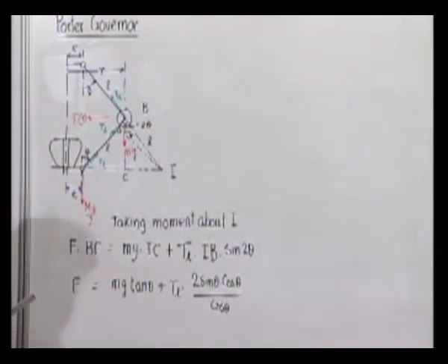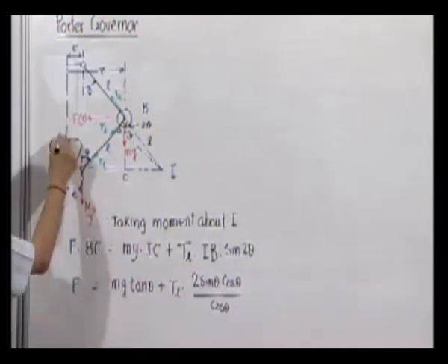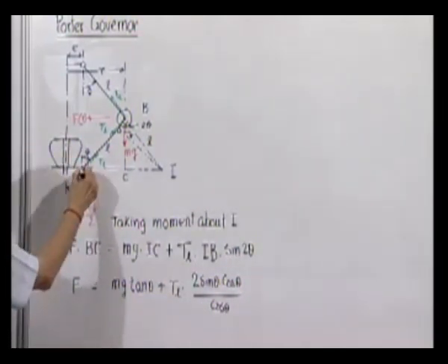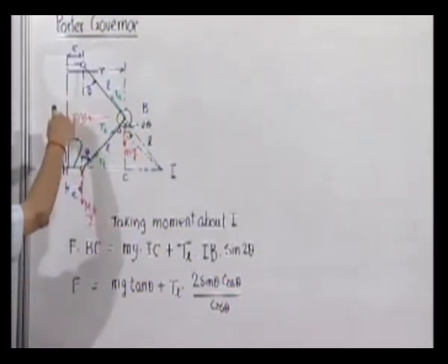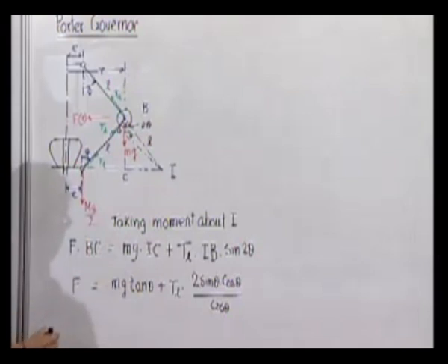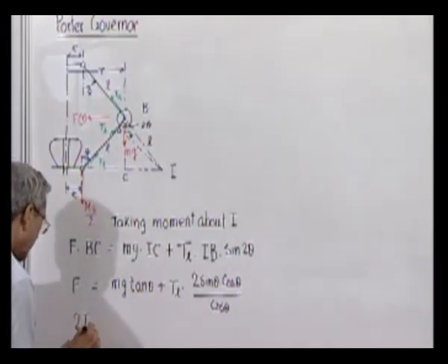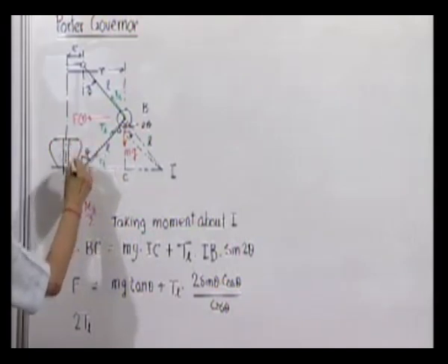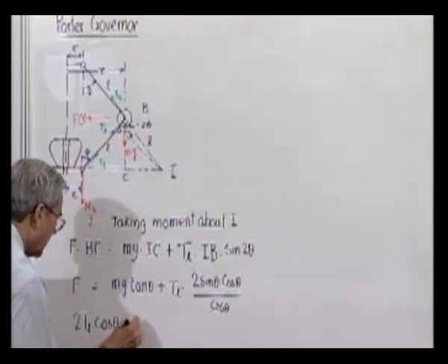We also know, now therefore, the question is how much is TL, that is still not known. But if we consider the equilibrium of this TL and another TL on this side, they are supporting this total weight mg. So, we know that 2 TL and what is the vertical component? Cosine theta is equal to mg.